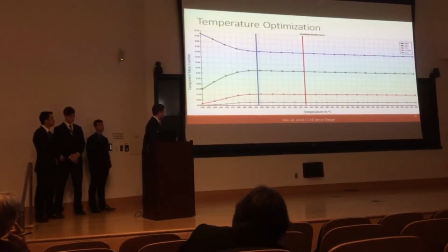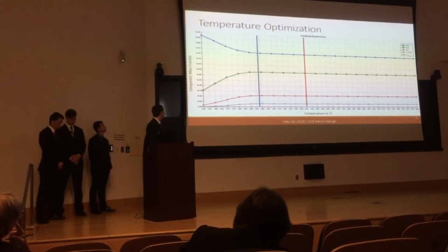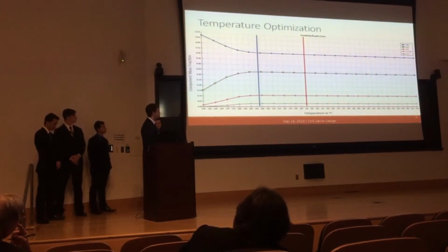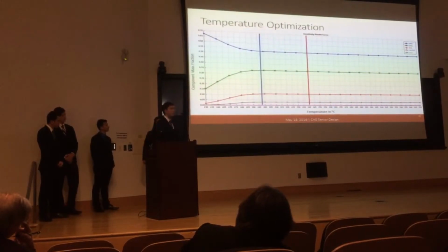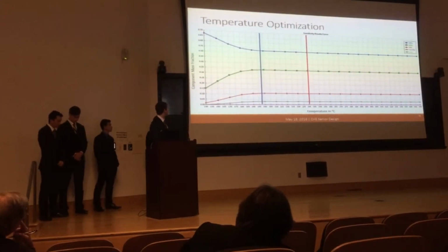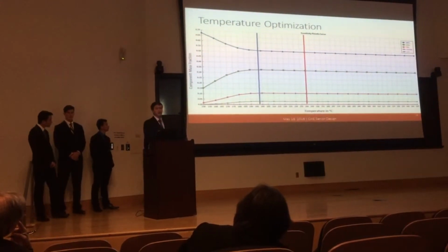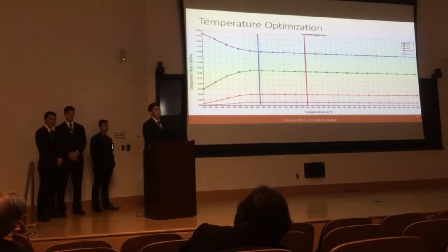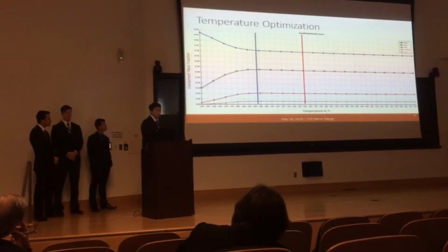After coming up with the ratio, we then moved to optimize the temperature for each of the reactors. From the literature values, we started off with a temperature of around 240 degrees Celsius for the first reactor. Using sensitivity analysis, we were able to bring the temperature down and achieve the same exact composition at around 197 degrees C, greatly reducing energy costs and utility costs for the entire project.